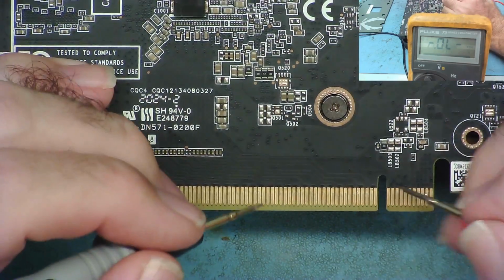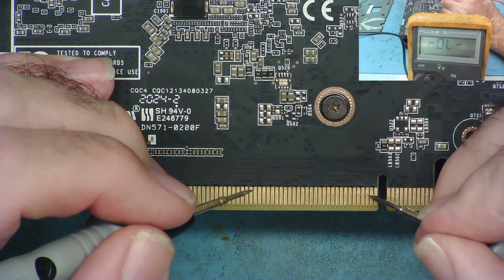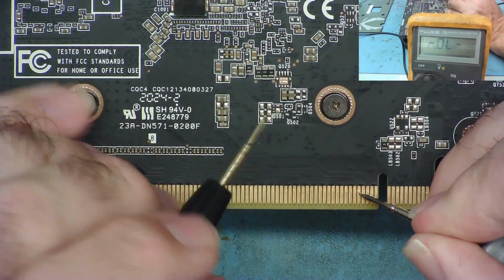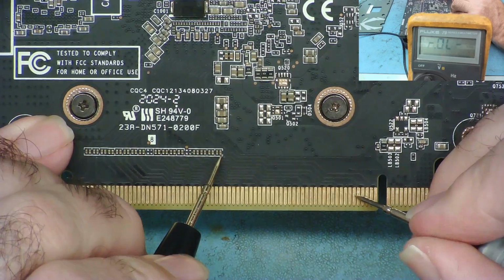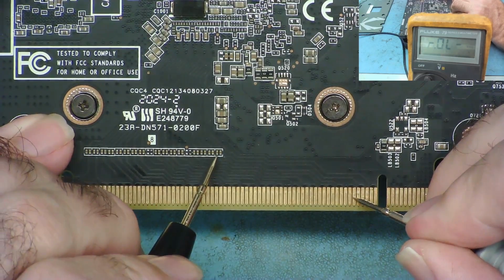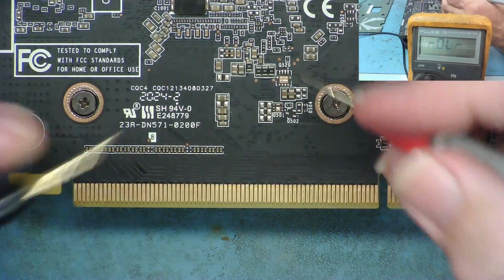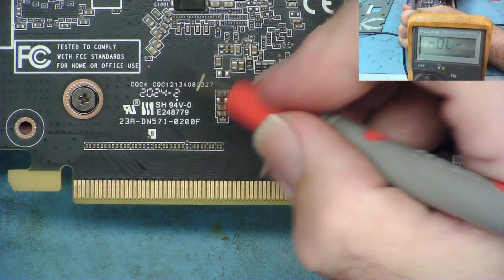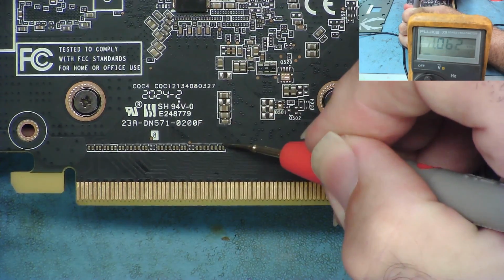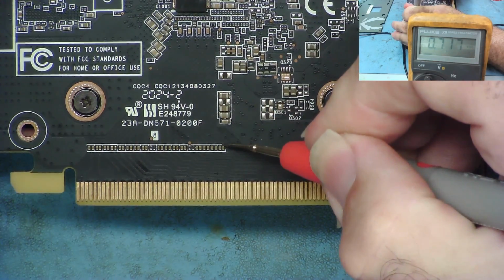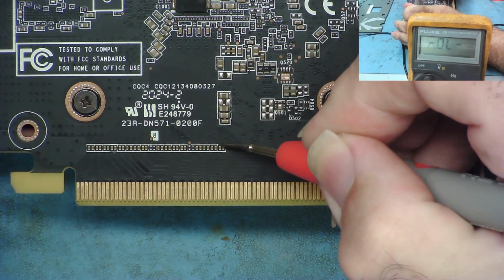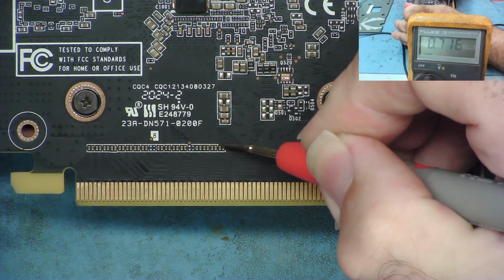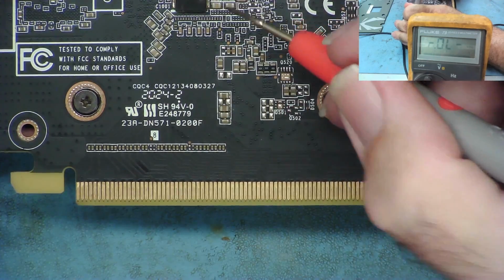So we'll have a quick look. I'll show you, from pins 1, 2, 3, 4, pin 5, we'll go to the capacitor. Here, yeah, and pin 6 will go to the capacitor afterwards. Okay, and then from the other side of the capacitor to ground we have. That's how I'd expect it to read, with a bleep, yeah, and steady. Yeah, that's how I'd expect it to read. They're okay. Let's have a quick look on the other side again.